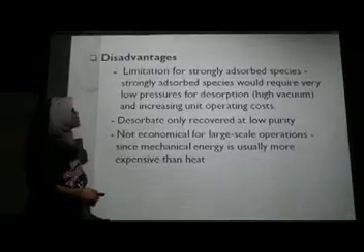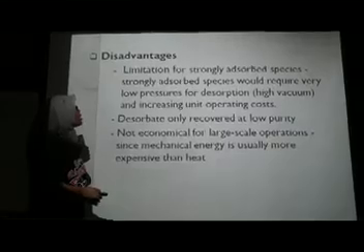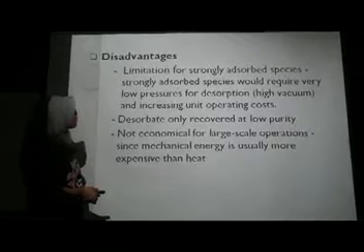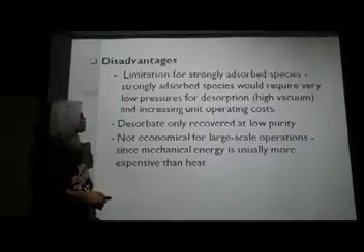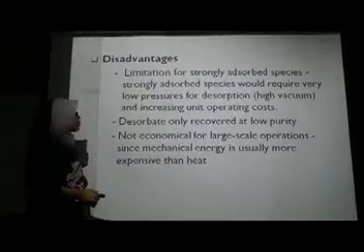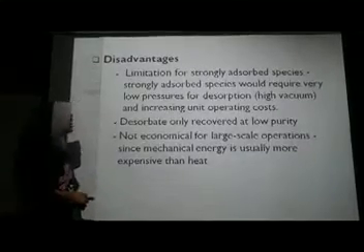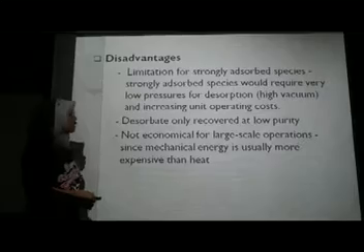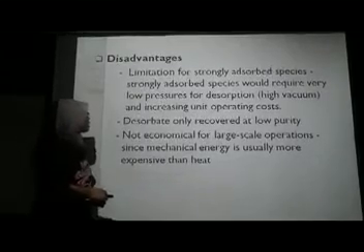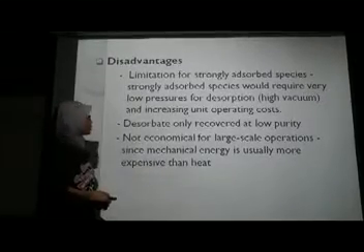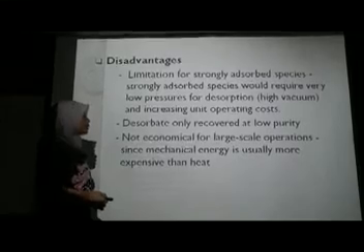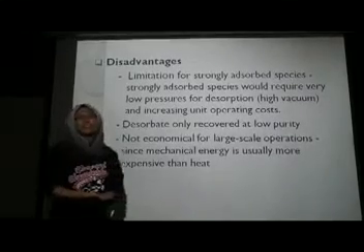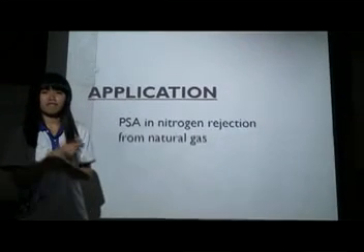The limitation: strongly adsorbed species would require very low pressure for desorption, increasing unit operating costs. Besides that, desorbate is only recovered at low purity. It is also not economical for large-scale operation since mechanical energy is usually more expensive than heat. Thank you, Shafika, for the presentation just now.